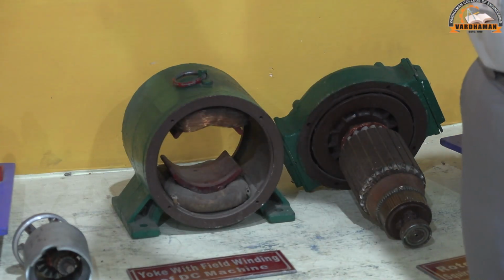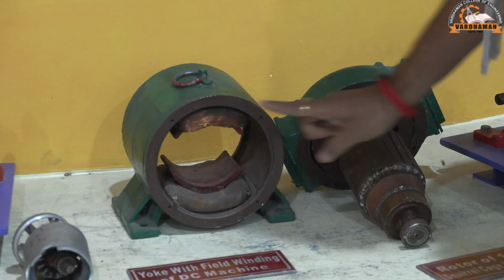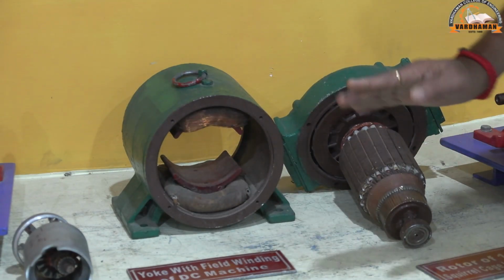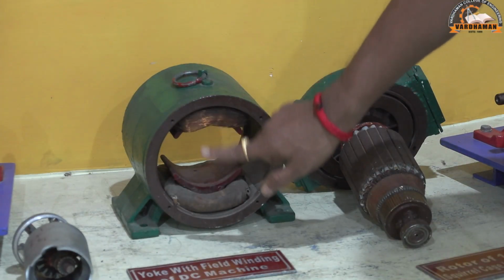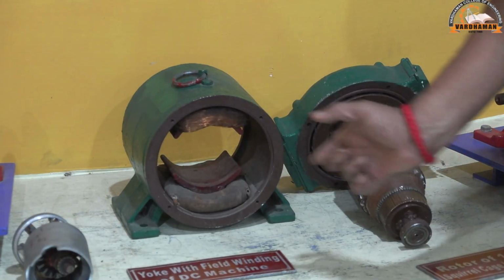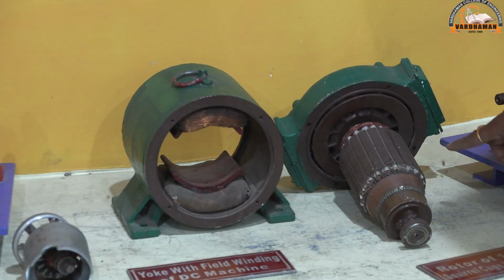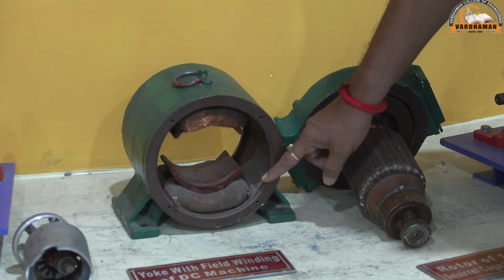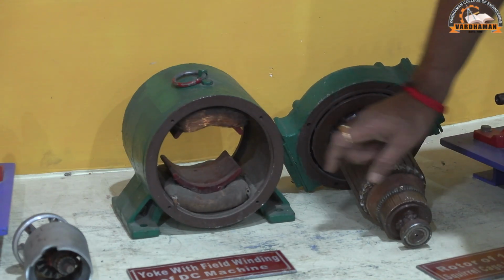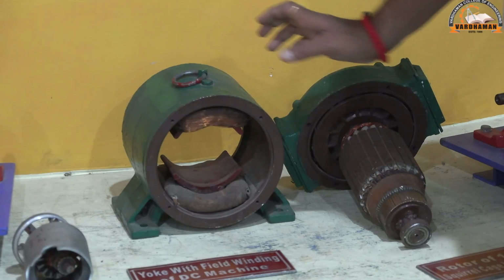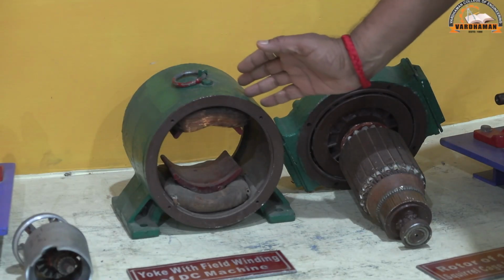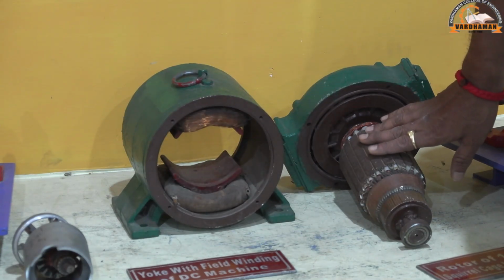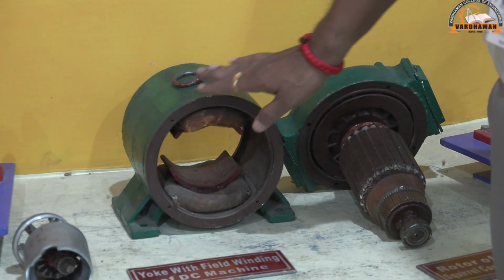If the winding coil is connected in series with the armature, it is called a series motor. If a motor consists of a shunt field as well as a series field, both in a single motor, it is called a compound motor. So, depending on the excitation, self-excited motors are divided into three types, depending on the connection between the field coil and armature. Parallelly connected means shunt motor. Series connection is series motor. If a motor consists of a series field as well as a shunt field, both in a single motor, it is called a compound motor. Three varieties of motor.